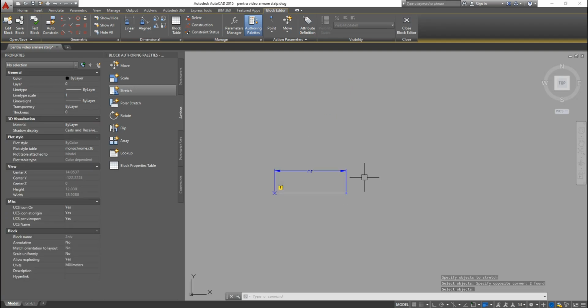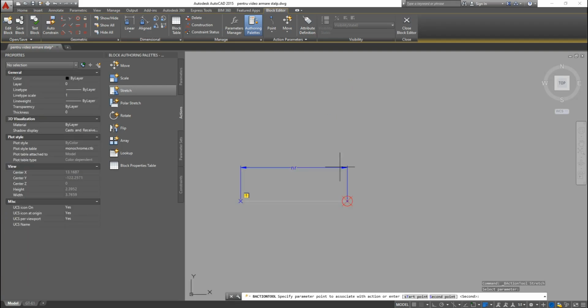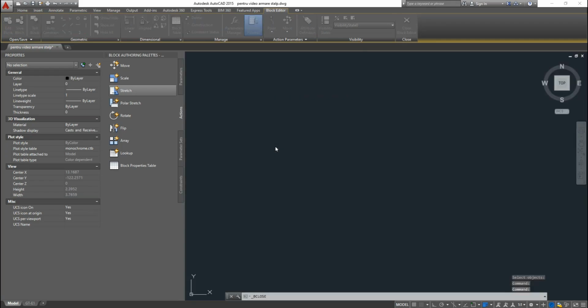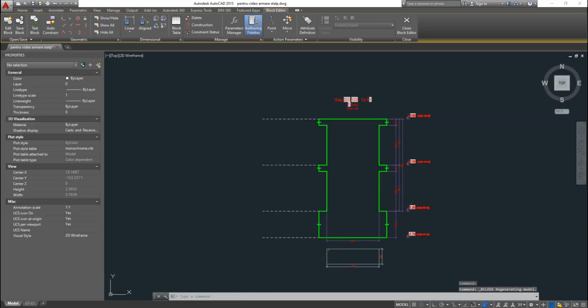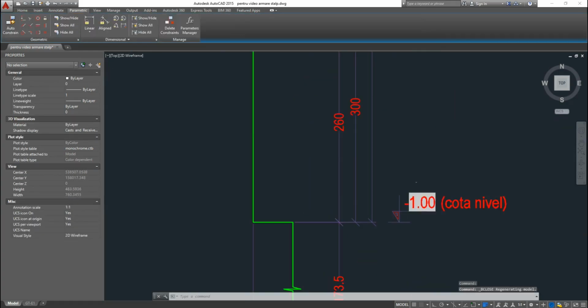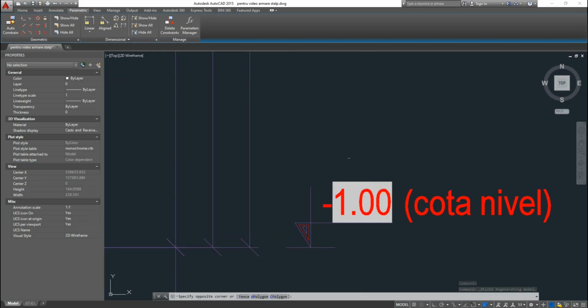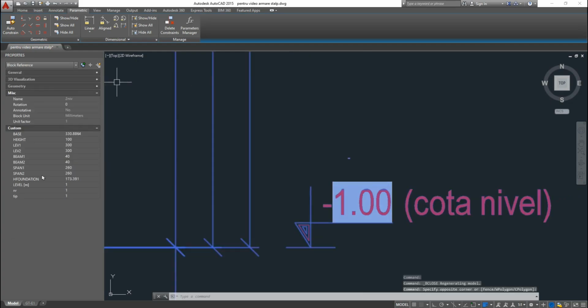And also for the number. Now let's see from outside, close and save the changes. So now if I'm coming here closely, I'm pinching the block from somewhere, I'm going to the level, and I already have the minus in front, and I will just go and say 0.1 meters, meaning that I have the column with the concrete starting from minus 10 centimeters below the